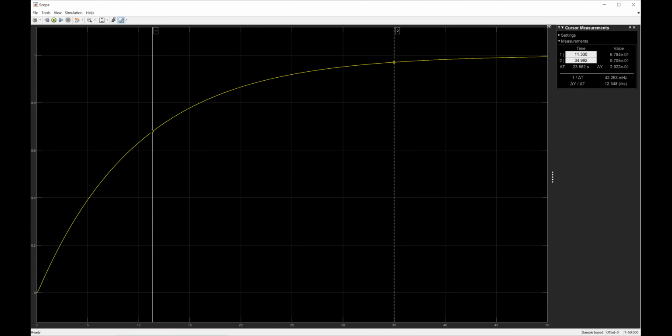And you would realize that now the time constant has become 11 seconds. Initially my time constant was 1.6 seconds. Now it became 11 seconds. So the system has become super sluggish. If I add damping, the system becomes lazy, sluggish.